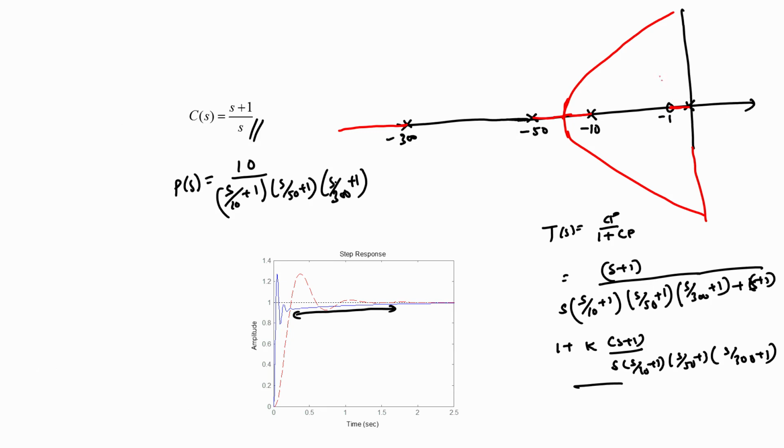So, we would have one closed loop pole on this branch, one closed loop pole on that branch, one closed loop pole on that branch, and one closed loop pole on this branch, the branch near the origin, and it is that closed loop pole which is of interest to us, because if I were to represent T(s) in terms of these closed loop poles, I would have T(s) equal to (s plus 1) divided by (s plus alpha), where alpha is a point here in between the points minus 1 and 0, times, if I call this point P1 and that point P1 bar, and if I call this point P2, then we would have (s plus P1) times (s plus P1 bar) times (s plus P2).